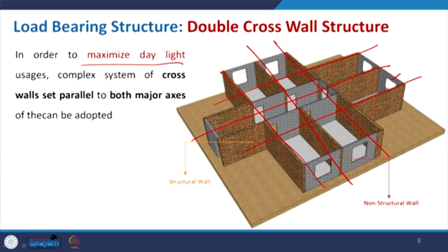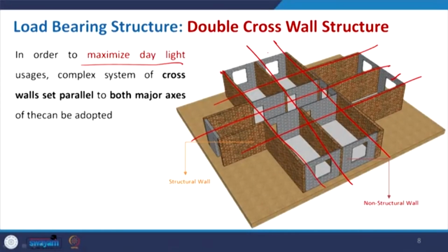It is also very common, where you actually see apartment buildings or small residential buildings. But at the same time, when you go with a very regular shape, distribution will always be easy. Suppose I want to make the plan of this. Basically if I draw, these are the structural walls, and then you have the connection, and the thinner one is basically your non structural wall.